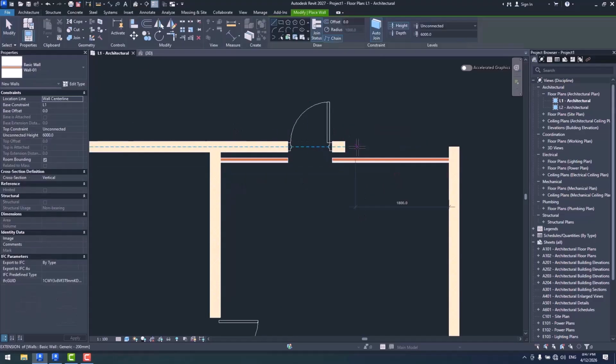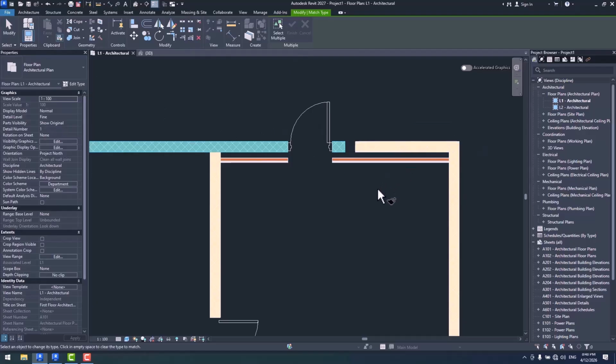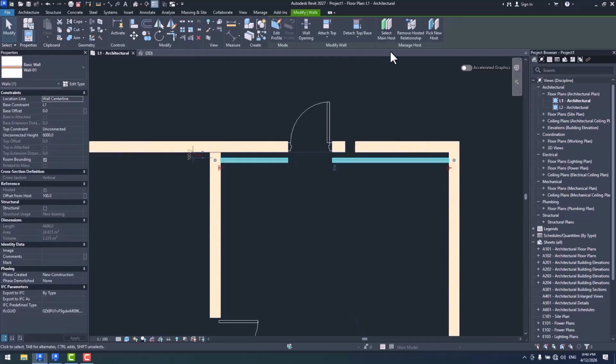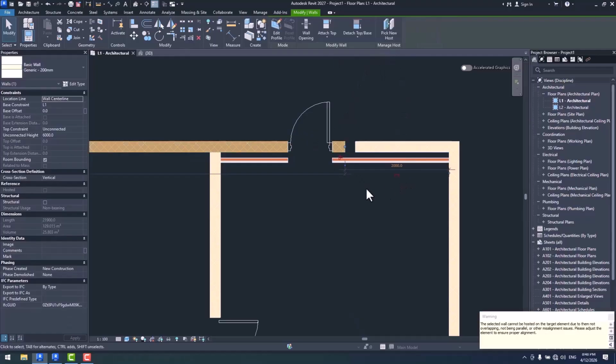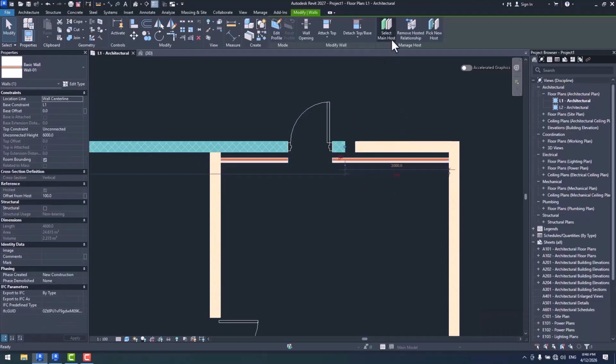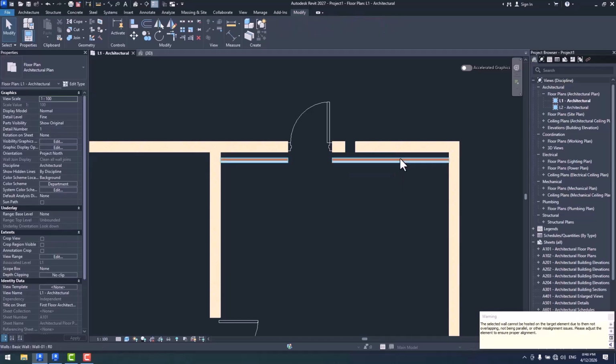I mean, basically, if we go with this select main host item, we'll be getting the main host, and then if we go with pick new host, we would be able to, for example, select this one as the host. Alright, it didn't work. Why do you think it didn't work though, guys? Well, the warning says we are not dealing with completely parallel walls. So let me try applying some modifications to this whole thing.